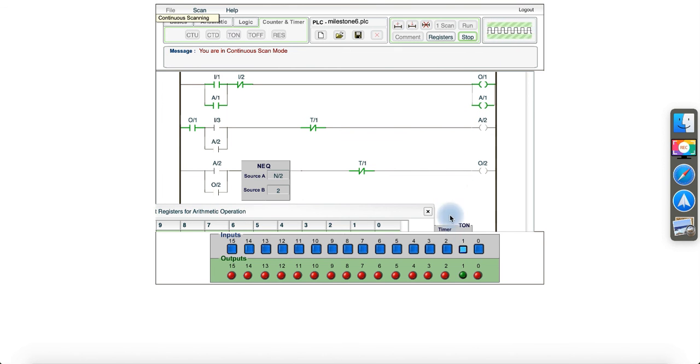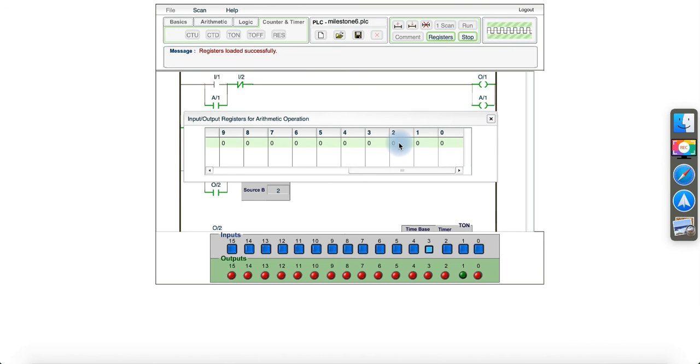Just to test the emergency button over here, if you press it, the motor switches off. Okay, once it's pushed back off, the conveyor turns back on. And since normally in machines the buttons are release buttons, that's why we use the relay A1, so that after the button is released, the conveyor is still running. Now, input 3 detects a value, which is the value that I plugged into the register, which is the value 2.